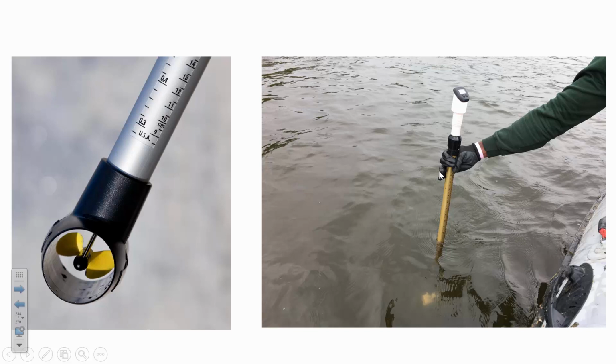And so to know the flow rate in a river, you'd have to take this device and measure at different locations in the river, all the way across from bank to bank, the flow velocity. You'd divide your flow area into segments, maybe at 1 meter intervals, find the velocity, and then assign the velocity to that 1 meter segment, multiply the velocity by how wide it is and the depth of the water at that location. And so that would be a way of numerically integrating the cross-sectional area of the channel to find the flow rate.